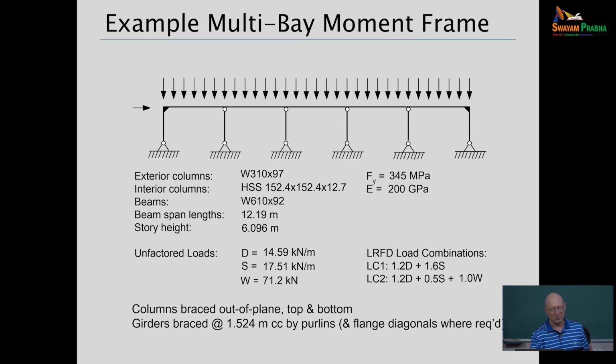For load combination 1, it's a gravity load combination, so I need to put in out-of-plumbness. I'm required to, or an equivalent notional lateral load, 0.002 Y sub i. For us, again, I see the Indian standard would use 0.005.